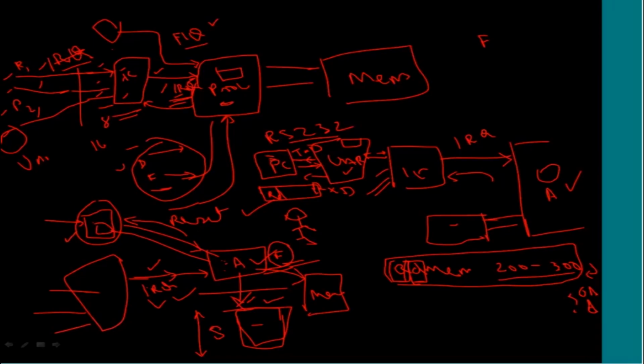So you can imagine how frequently this will be executed compared to this. Until the whole command is received, this will not be executed, right? For individual characters, it won't be executed. Only when the complete command is given is this executed, but it will take a sufficiently longer time to execute, correct? So now we have seen an example where first level handling and second level handling are required in interrupts.